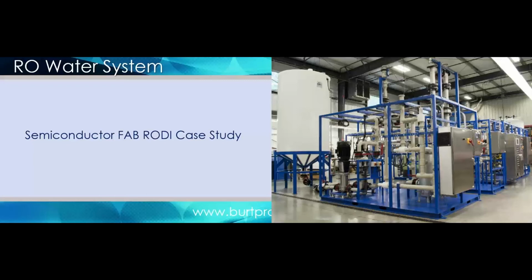How you do it with chemicals is simply ozone. You basically bubble ozone into the storage tank. You shut down the flow through the resin beds, and you really run it overnight through your system. You then turn the UV lights on. You can essentially destroy the ozone to oxygen at that point.